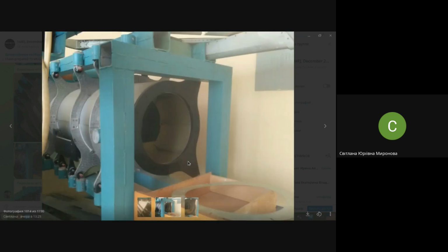Why do we watch all those diverse designs of jigs? In order to make you recollect and understand basic points. We have a so-called skeleton, we have a system of locators, and we have auxiliary devices. And all those elements should be in proper spatial position. It's also a mock-up of the jig, not the real one, also approximately the same height as me. Pay attention, the skeleton is, of course, welded roughly like a whole piece.